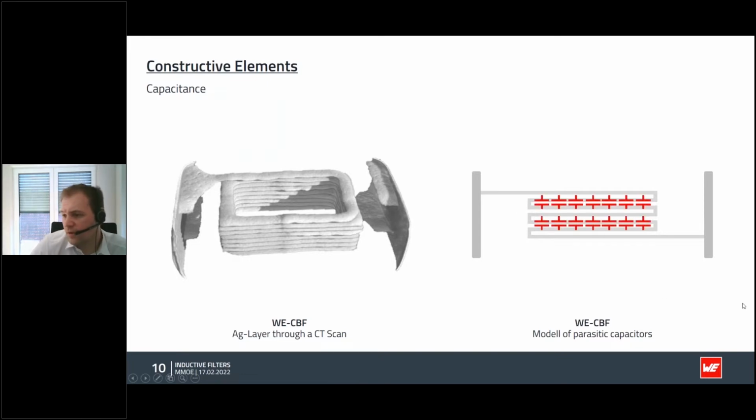However, for an SMD ferrite, this interwinding capacitance is shorted, and the capacitance between the actual winding and the SMD terminal of the component is dominant here. So this is what creates the bandwidth limitations for an inductor, and in this case for an SMD ferrite.